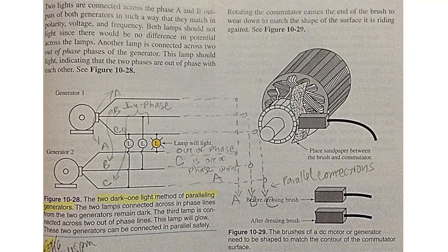Test instruments are needed to determine if the armature or field windings are good or bad. Usually a voltage equal to the generator voltage is used to check the windings for grounds. Most multimeters only use a 9-volt battery and cannot detect a ground created when 120 or 240 volts are present during generator operation. Heat from an excessive overload can also cause the generator pole pieces to lose their residual magnetism.